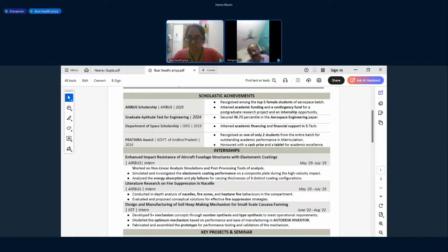Yes, sir. Okay. But you are telling the equation sigma is equal to My by I. But what is the correct way of telling it? You must write sigma XX is equal to My by IXX, like that. So you must always give the direction XX, YY, ZZ, because the stress in the aircraft is 3-dimensional. You must always do it like that.